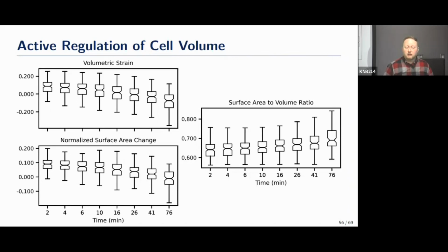You're saying at a higher rate of loading, there'd be less potential for that rigid motion of the cell going upward. Well, when you're that close to the draining surface, we like to say when you load something very fast, the water doesn't have time to move anywhere, but the water's still moving. So when you're really close to the draining surface, you're actually going to have higher fluid velocities there at the higher rate.